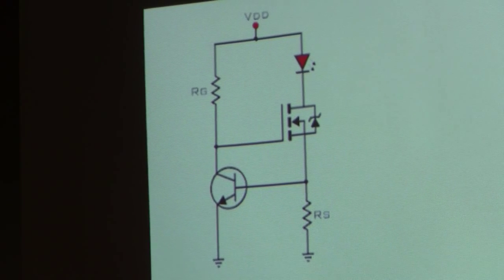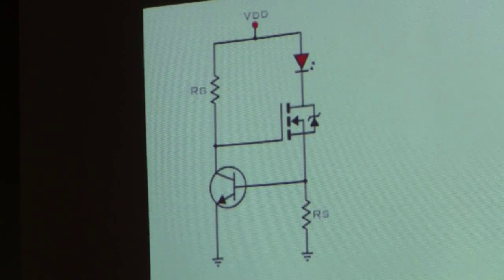So MOSFETs don't like having the gates floating in the middle? Darn good point. It's not in saturation or something? What you're thinking of is a CMOS totem pole output, which definitely does not like to be left floating or somewhere in the middle, because you get conduction into top and bottom and you get shorts. This is related, but not the same thing.